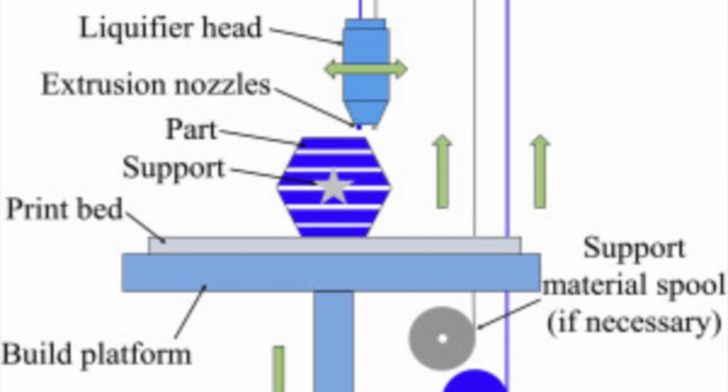The extrusion nozzle can move in both horizontal and vertical directions as it precisely places the material, following the blueprint of the digital model layer by layer. This process is repeated until the 3D printer has replicated every layer in the digital model with the extruded material.